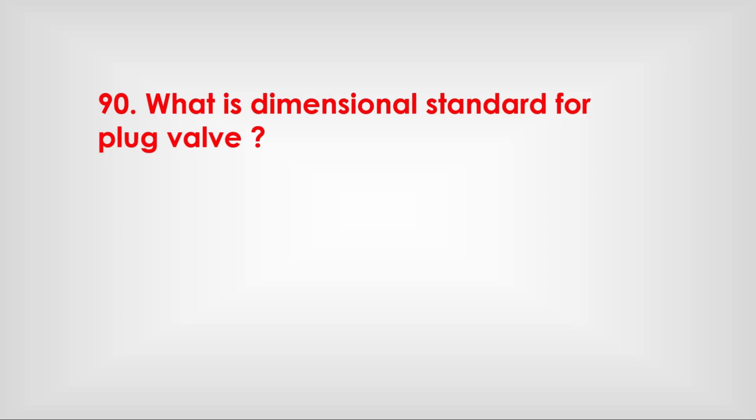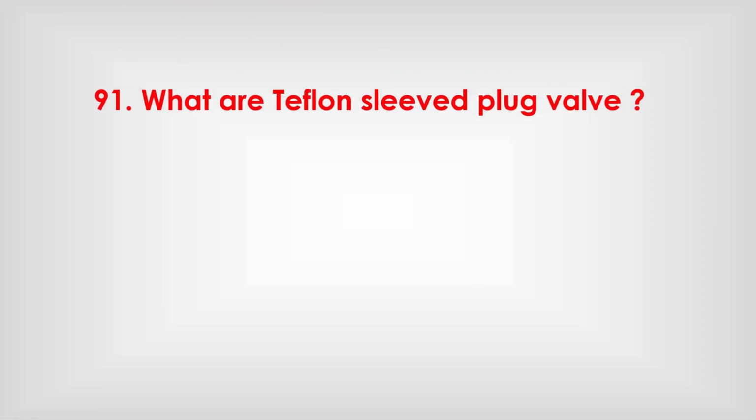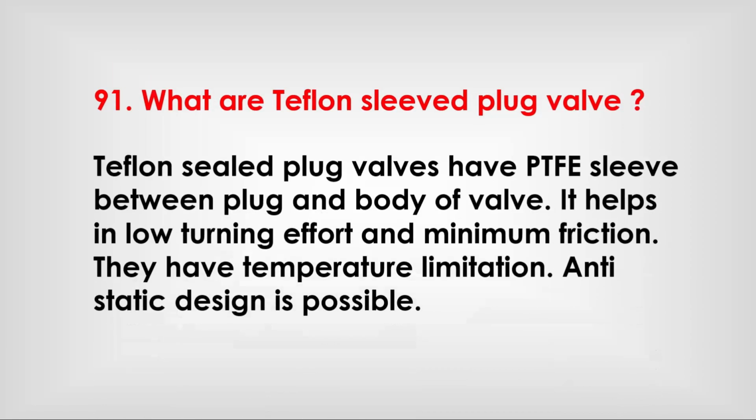What is the dimension standard for plug valve? API 599. What are Teflon sleeved plug valves? Teflon sleeved plug valves have a PTFE sleeve between the plug and body of the valve. It helps in low turning effort and minimum friction. They have temperature limitation. Anti-static design is possible.